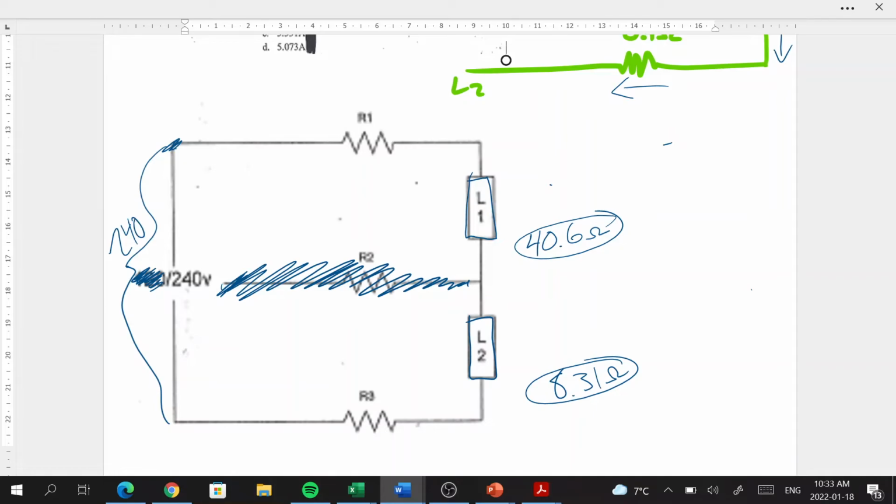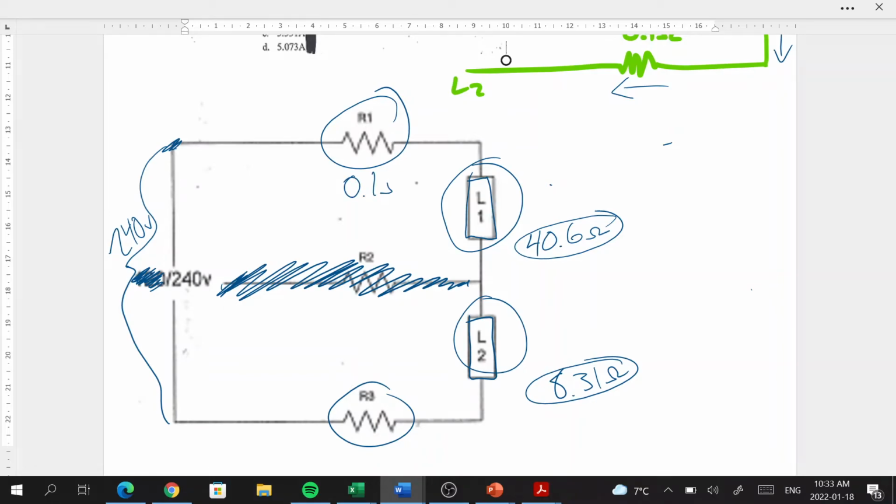That's it. And now what we're looking at here is 4 resistors essentially in series with one another. Now we know the resistive values of the conductors. That was 0.1 ohms and 0.1 ohms. The neutral doesn't matter anymore. It's open, so there's no current flowing on it. So we have 4 resistors in series with 240 volts.